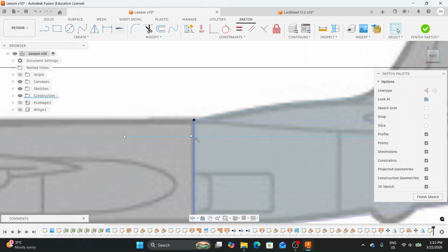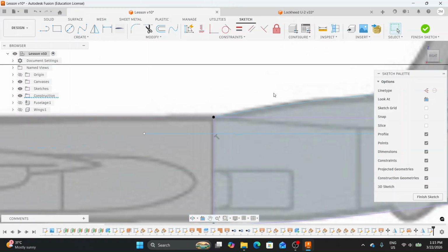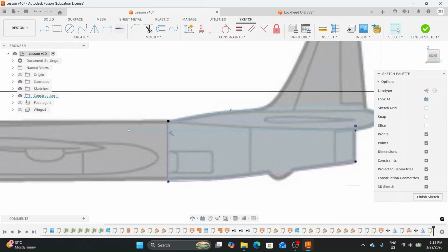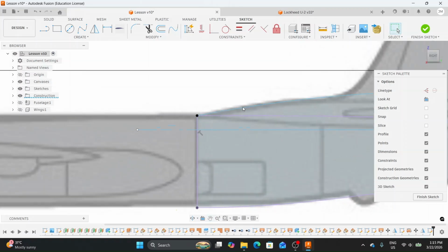And then one thing again, since we're going to be imagining this shape right here, for me, I'd like to make an excess so that later on when we trim this 3D body, this section right here looks flushed to the body, or seamless when you look at the body. So my technique here is that I'll extend this fit point spline that we have